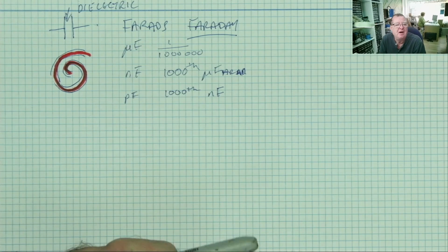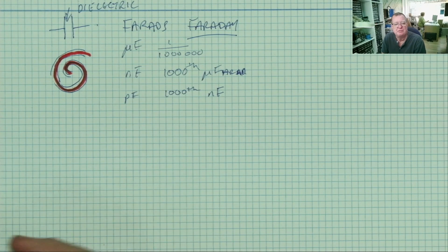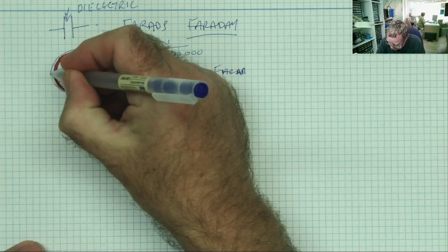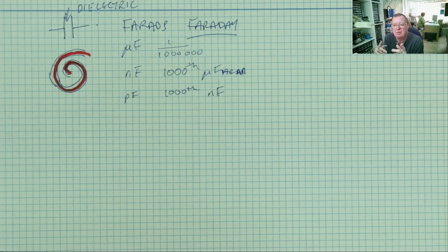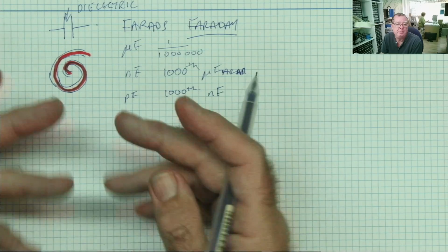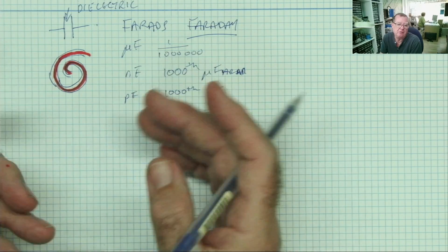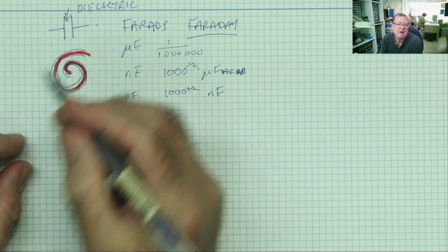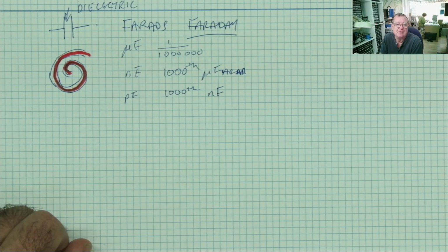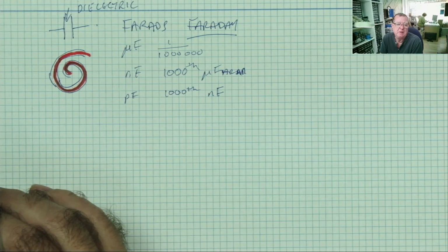Yeah, something like that. Imagine a Swiss roll, them things with jam in them, and cake either side. So the jam is the dielectric and the cake is the metal plate. I'm not sure how conductive cake is, and I'm not sure how well insulating jam is. Maybe you guys can go and find out, but that is the basic construction of a capacitor. So by rolling these things up using often aluminium foil and some sort of insulator, you can make larger and larger capacitors. So the area of the metal plates is the first factor, and the higher the area, generally speaking, the higher the capacitance.